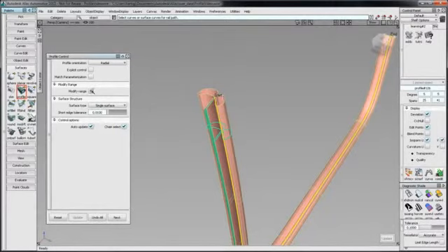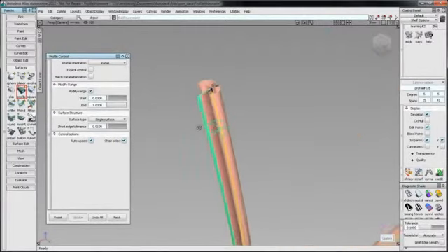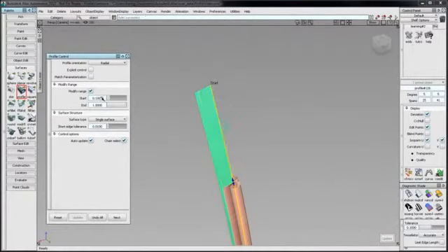Modify range allows adjustment to the start and end of the profile surface. A value can be entered. The start and end sliders can be placed visually, or the sliders will snap to the red X's along the rail at curves on surface and isoparms.